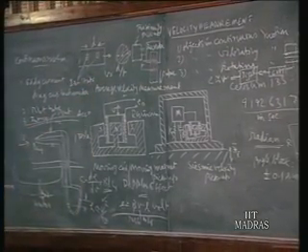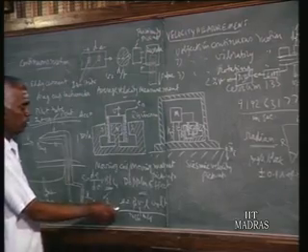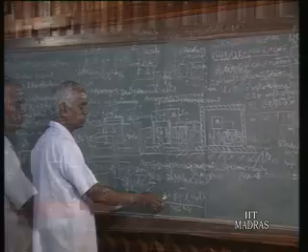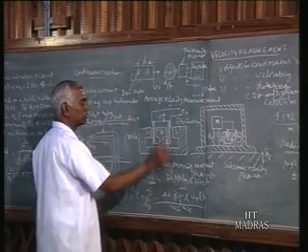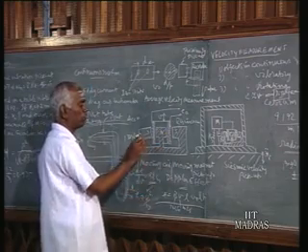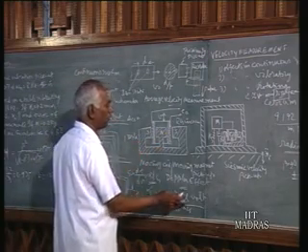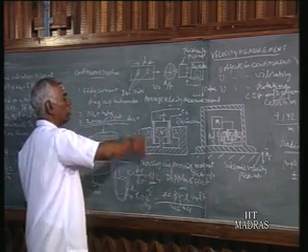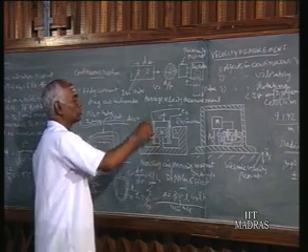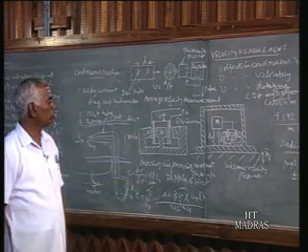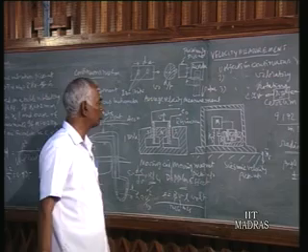Yeah, moving coil, moving magnet pickup. It is a simple principle. Voltage developed is given by flux density times relative velocity of the coil with reference to the magnet times length of the wire. So as the coil moves up and down, it cuts the magnetic lines. So voltage is produced proportional to the relative velocity of the coil to the magnet.